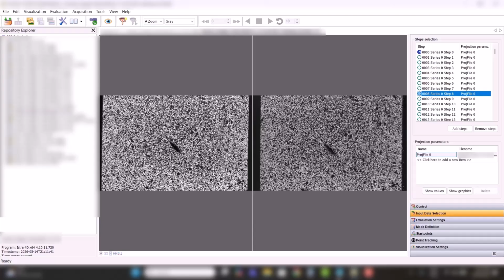If there's been a large amount of deviation from active images to the reference image, then rung steps are used to bridge the gap from the active image to the reference image, because if there's too much of a difference in the image, that can degrade the performance of the DIC correlation. That's the purpose of rung steps.